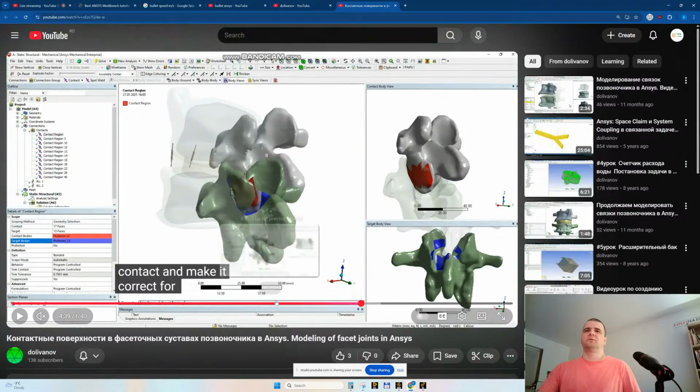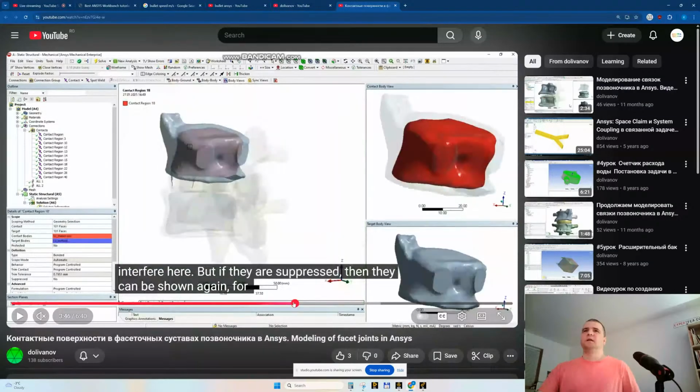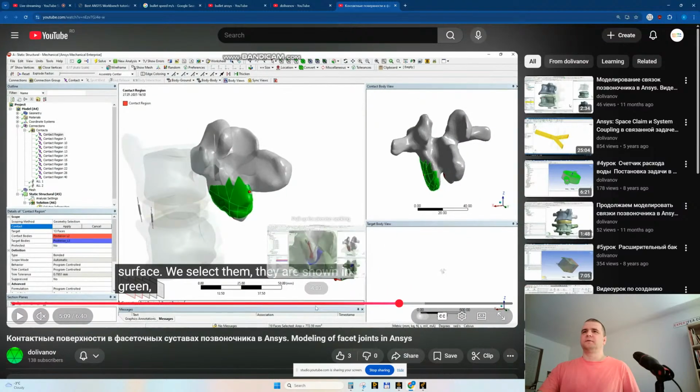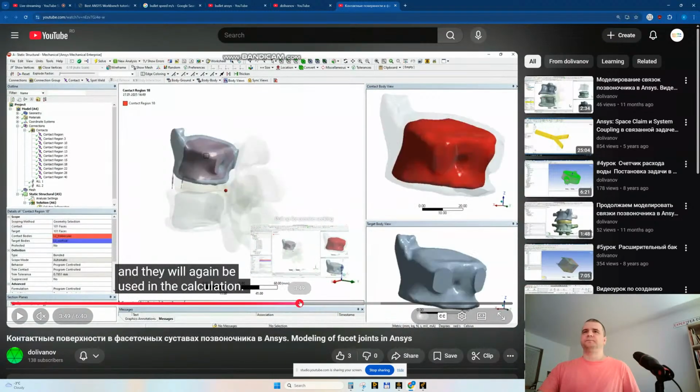There should be bonded contacts, and also there should be bonded contacts inside. Look here. Because here should be bonding contacts, because he has different material densities, yeah? So between the spongy and the cortical part, but here, of course, it should be bonding contacts also here. And also here in the cartilage, because he has 2 different cartilage densities.